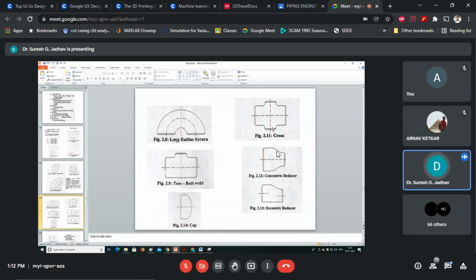The both ends flanged are used where welding is not possible or not permitted in piping industries. Normally, these are made by castings. Maybe you heard the terminology castings in manufacturing engineering.